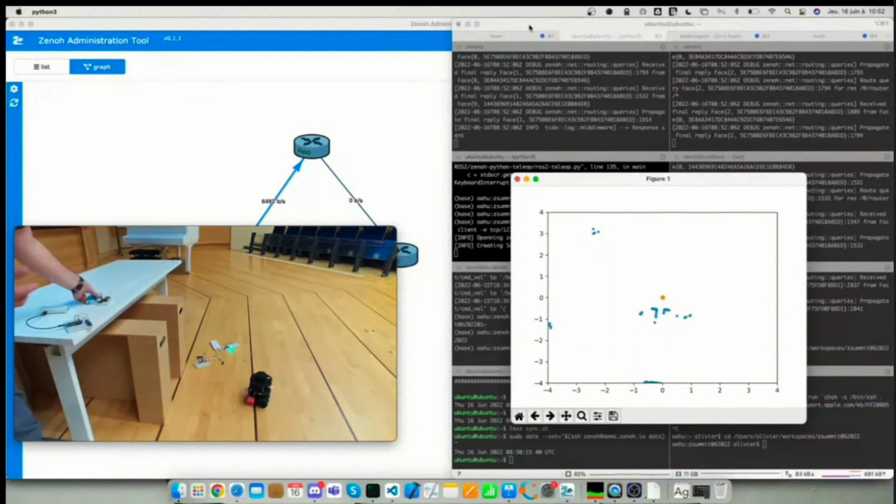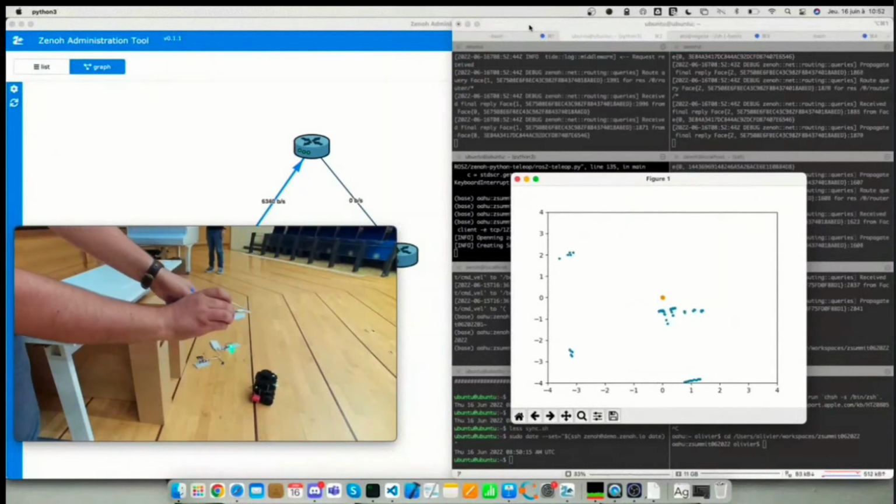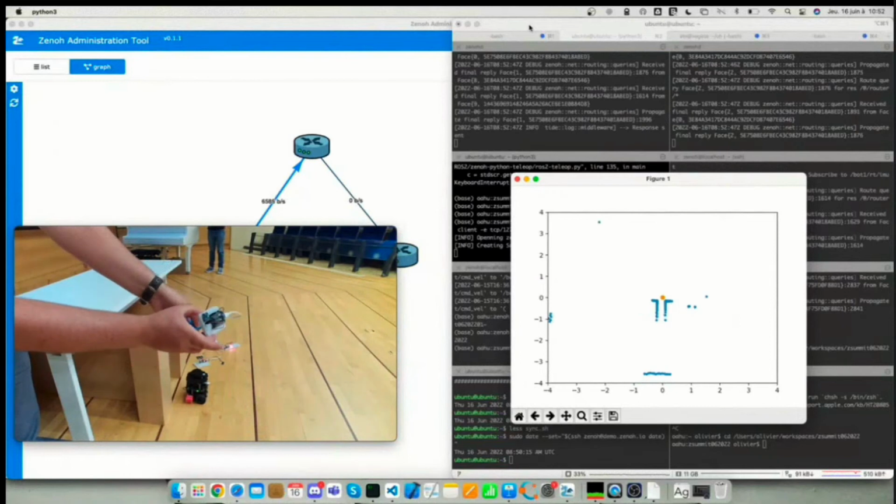So that we can do sensor fusion of all these sensors that we have in the factory, integrate them with the control of other operational processes that we also have in the factory, and be able to have finer control of what happens. So in this case, whenever something is too close, we block the operation of the robot. If the sensor is green, meaning there is no object in the range, the robot can move freely. So if we see it now, he's far away from the fence, so we can move it again. If you go close again, yeah, the sensor turns red and it stops.